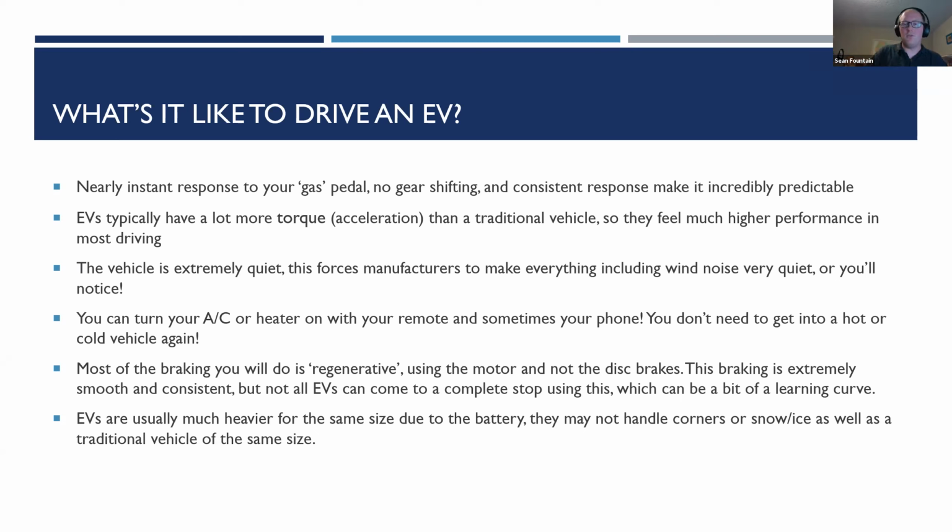And you also had neutral, so it can be towed up onto a tow truck and stuff. But the low tells the motor to do the regenerative braking much more aggressively and down to a lower speed, to get as much electricity back as possible. What happens there though, is when you lift the gas pedal off, it starts braking, not really hard, but a fair bit.